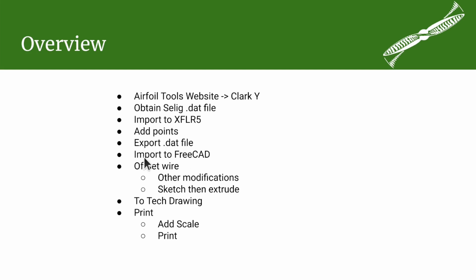And then what I will do, and you could use a different program, I'm going to import it into FreeCAD. FreeCAD makes it pretty easy to do that. In some cases, you don't want the outside dimensions of that airfoil. You're going to want something inboard, inside, just a little bit. For example, you want to maybe subtract out the thickness of the wing skin and thickness of a flange of your aluminum ribs when you want to form an aluminum rib. So we'll go over that.